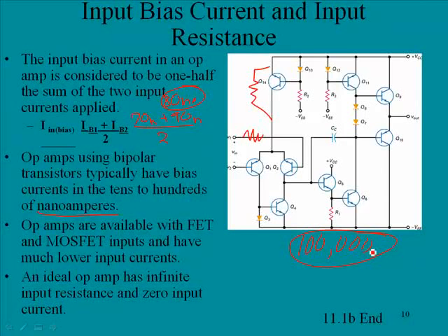So commonly in op-amp designs, on the input you'll see a resistance here, and then they'll have another resistance here that will appear to have no apparent purpose, but its purpose is to equalize those voltages that may be developed from those tiny input currents.